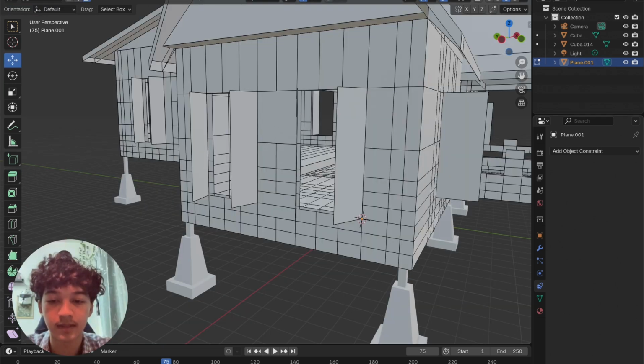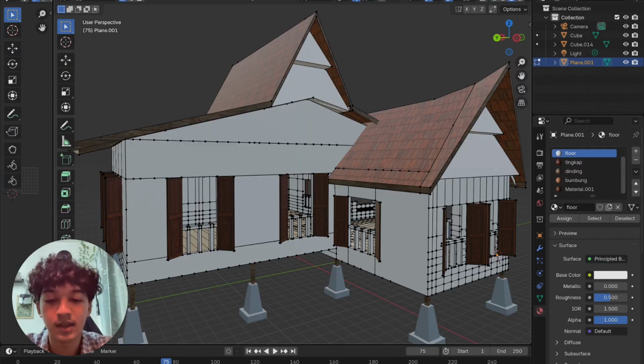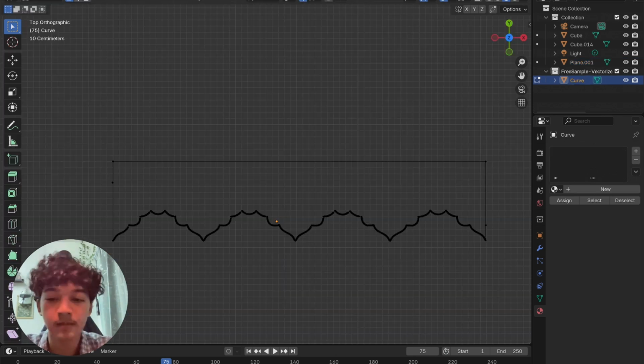And for this part, we added an open door to every window. Then we add rails to every window, with it being almost half the height of the window, just like any other traditional house designs. Then we add colors to the windows, footings, roof, floor, fascia board, and also remove all the excess vertices and edges to make the texture adding process easier.